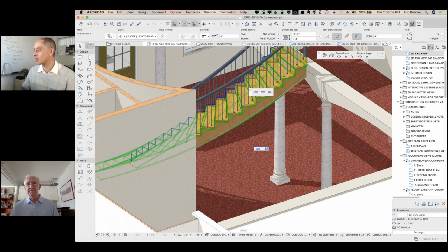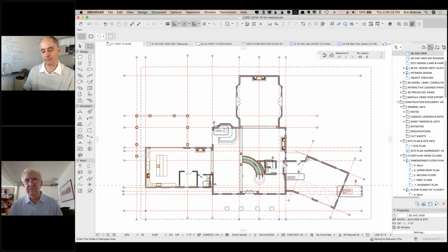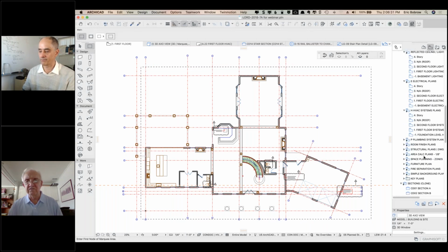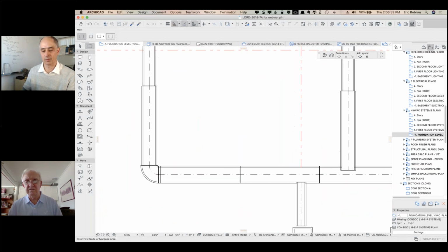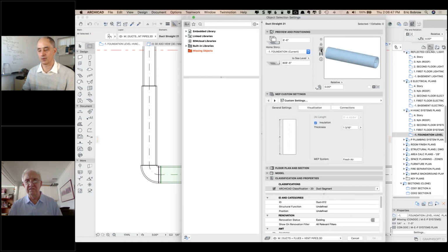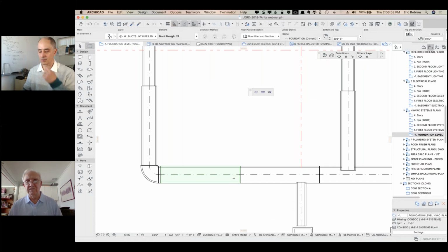Let's see, there's a couple other comments. Mark Wren says, we may have just said it, but how did you do the duct work? So you want to just talk for a minute on that? It's relatively easy. You buy the MEP add-on to ArchiCAD, put it in, and it has a whole package of every conceivable duct configuration you could imagine: squares, rectangles, rounds, flexibles, and all kinds of other stuff. And you just figure out the size and away you go, because they're individual pieces, and you just stick them next to each other, and they're fully adjustable, and you can do transitions. It's got every single part that you could possibly want to have in an air conditioning system. So it's relatively easy. I'm not a genius on this stuff. It's just step 1, step 2, and you get something done.